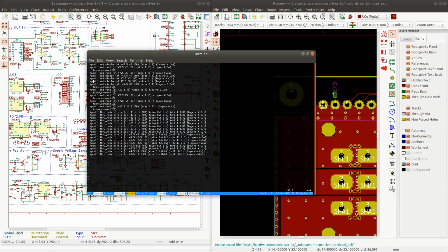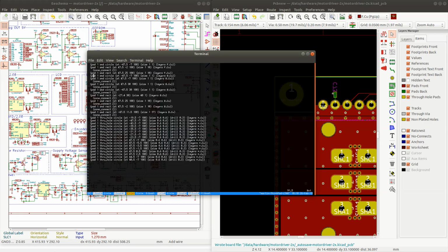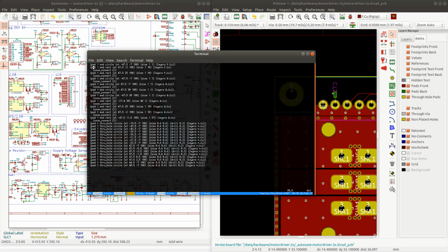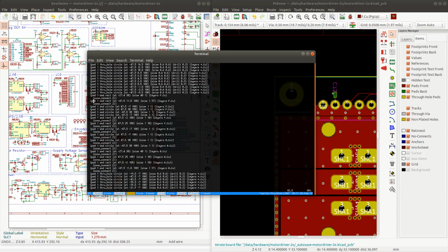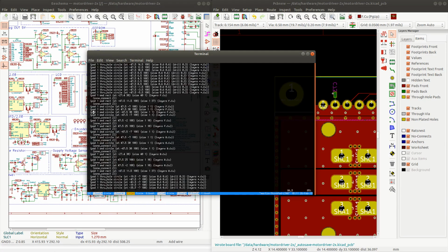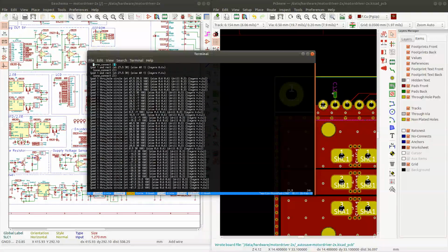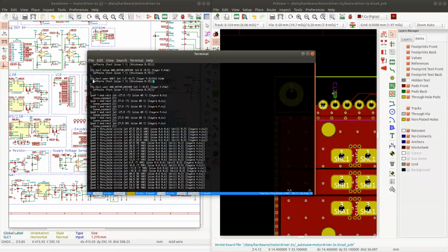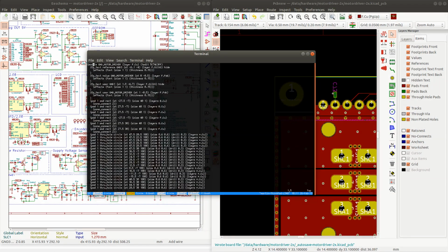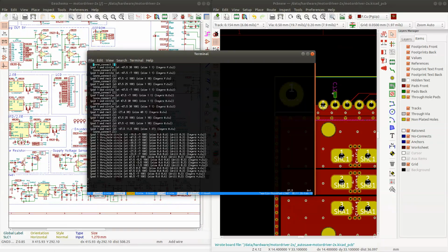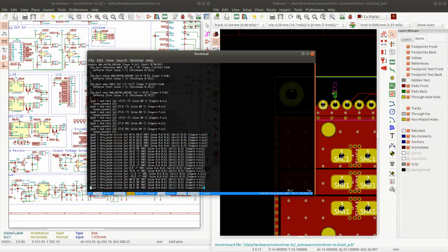Even on the circles. Like, this is insanely hard to do in the GUI. Because when you click on an element, you actually have to choose which one you want to select first. So it's absolutely unjustifiable to do this in the GUI. So we got zone connects. I think I changed all of the zone connects. Yeah.